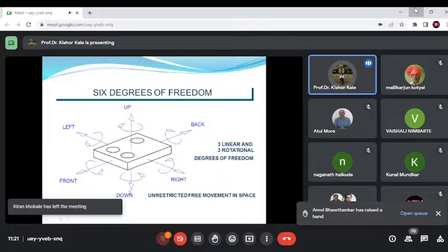That means if we have to select, it is not necessary that this bottom plane surface A will always be the primary datum. You can call this vertical also a primary datum, but in that case there should be an important basic point. We should ensure that it has a functional relationship defined with respect to all remaining parts. Here it is very easy because we can measure the height, depth, and width very easily with respect to plane A, not with the others.